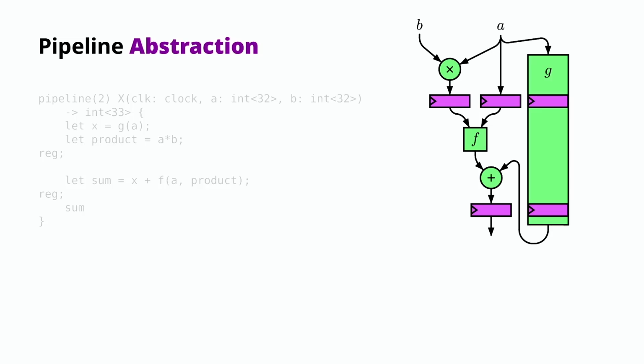And so with Spade, if you make this change, you compile it. The compiler will first tell you that this instantiation of G is wrong. You can't instantiate a pipeline as a function. You need to specify its latency. So you add the inst of 2, and the compiler will be happy with that part. That, of course, hasn't changed anything. The language could omit this and just do the rest of this analysis anyway. Because the real problem here is, of course, this backedge, the red one, that feeds back through a pipeline stage, and that's going to break everything.